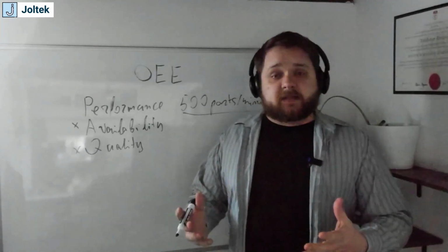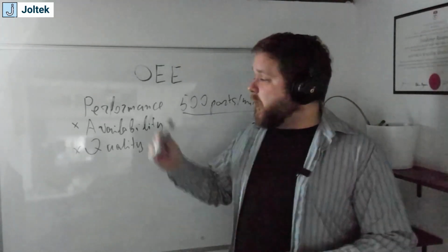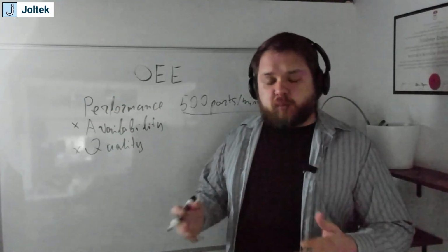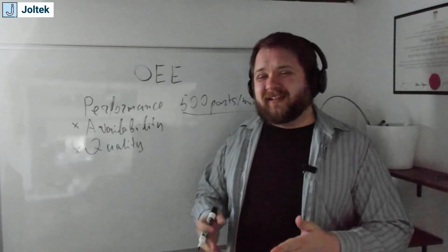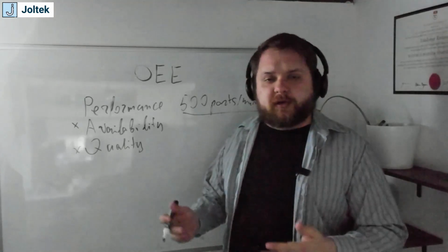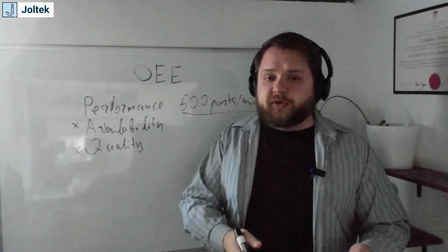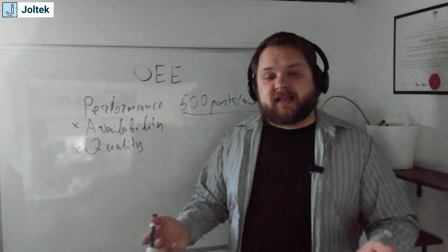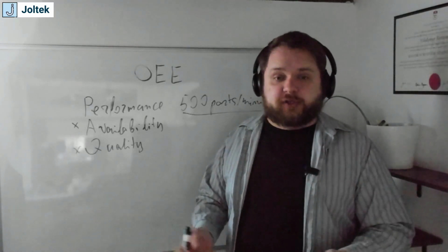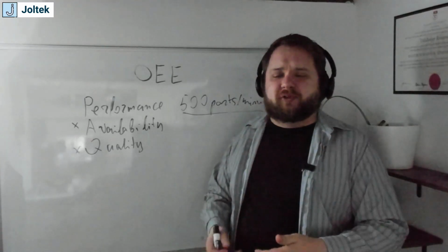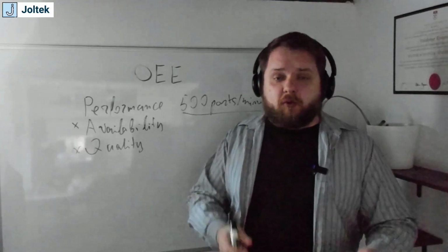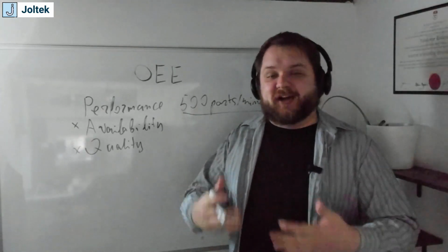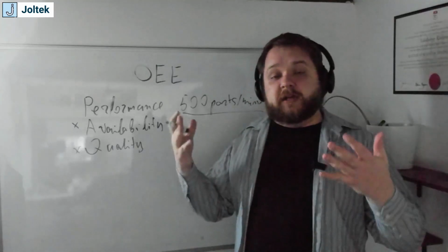The last conversation point that I do want to address is how often you should be pulling OEE from your equipment. And as I've explained a couple of times now, OEE is a fairly lagging indicator. There's very little you can do besides resolve the fault that you currently have on the line, reset the machines, and then start going. You obviously can resolve a deficiency in quality, for example, but that's not really going to be looking at your OE. You're going to be looking at the quality metrics on the number of rejects, and you're going to have a very different trend line, hopefully, on your machine and on your equipment to figure out some of those issues.